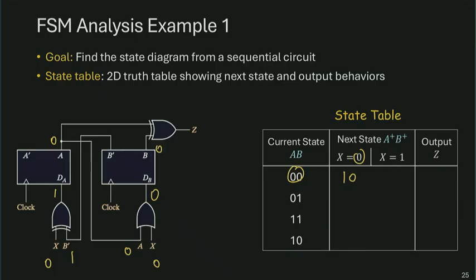Any questions before we move on? So I'm running some simulation. Again, I think about the evaluation of a sequential circuit in 2 stages. Number 1 is through this combinational circuit to get the flip-flop inputs ready. And a D flip-flop is like a transparent flip-flop. Therefore, the next state will be exactly the same as the flip-flop inputs. Any questions? All right, I'll try another example.